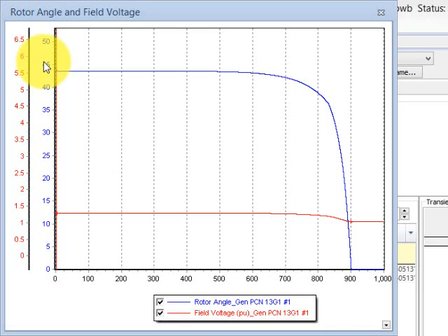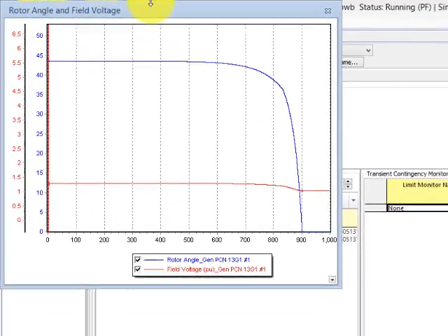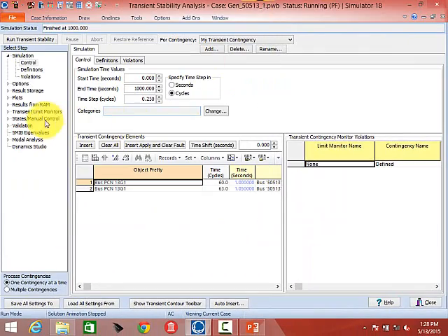But that's one where you're using this in a longer-term simulation, and suddenly stuff screws up at 900 seconds. There's nothing associated with that. That's not due to numerical instability. That's due to an actual mode. We've confirmed it with eigenvalue analysis. We saw it with the simulation, so it's there. The solution is just to fix the data, and let's say that really was just a typo.